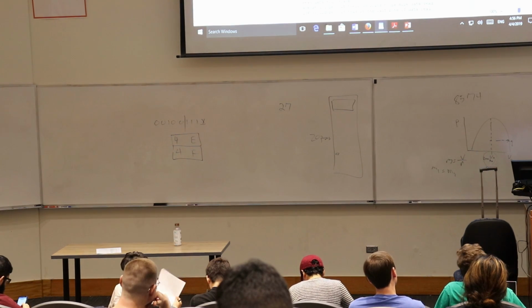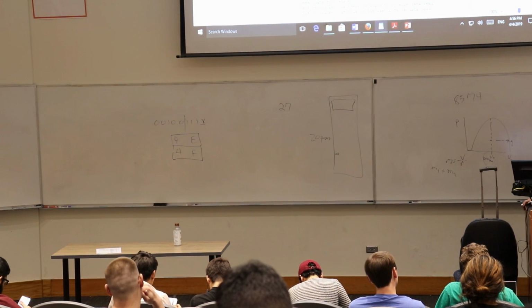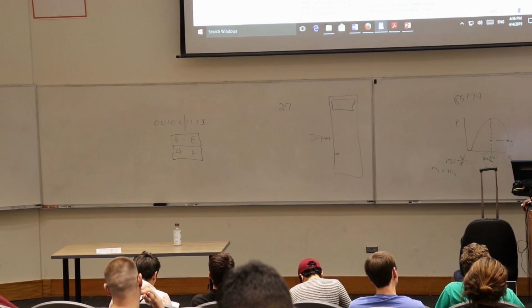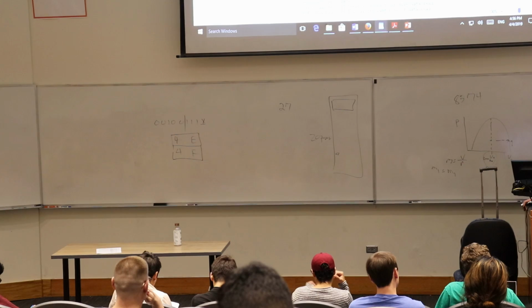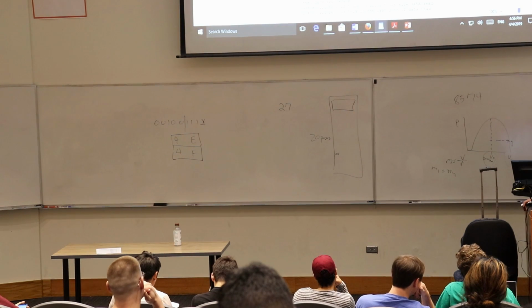And of course you typically have to set this up. Usually, on the accelerometer, first you send out the address and a write bit, and then you write out the register you want to start reading. In this case, it's register 1. Register 0 is a control register, so if you want to screw around with the device, you write a 0, and then you can adjust the registers.